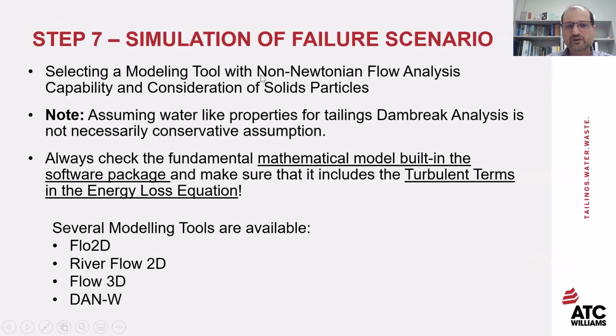Step 7 will be simulation of the failure scenario, selecting modeling tools with non-Newtonian flow analysis capacity and also the capacity to consider solid particles. Assuming water-like properties for tailings dam break analysis, we have to remember that it will not necessarily produce a conservative result. Always check the fundamental mathematical model built into the software package and make sure that, as a minimum, it includes the turbulent terms in the energy loss equation.